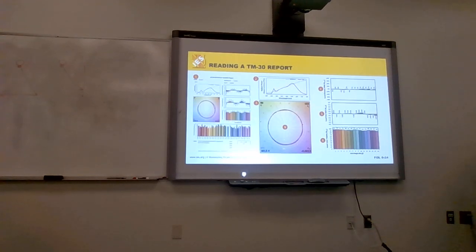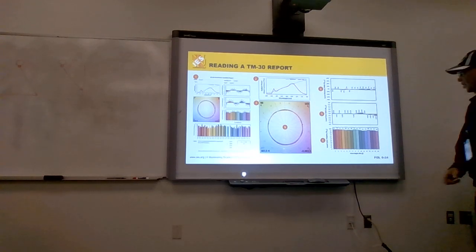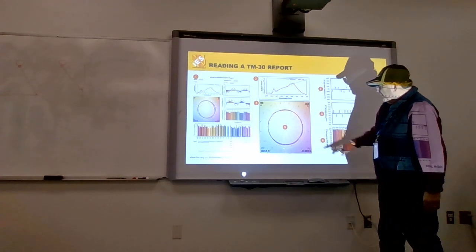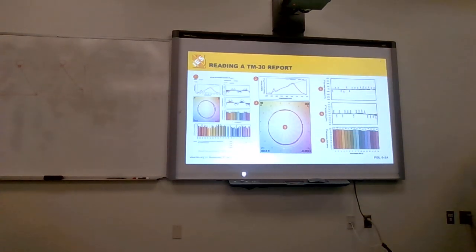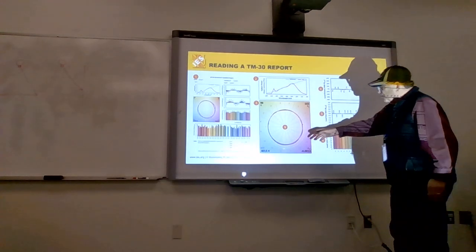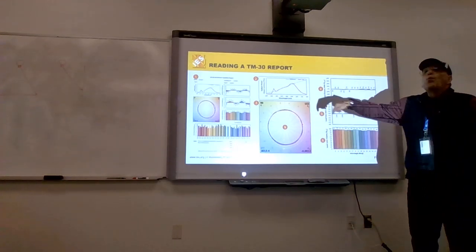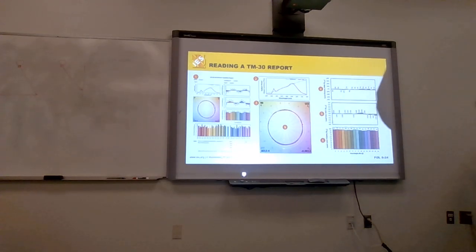We covered this already. This is the TM30 report. Again, we have 99 color bars in there, and we evaluate how close they are to a perfect circle. And as you can see here, this is a pretty good design because we have very little deviation from the perfect circle. That gives you some insight as to the qualitative aspect of the luminaire itself. The further away we drift this red line from the black line, the worse the quality of the light is, the less accurate the light is in terms of rendering color.